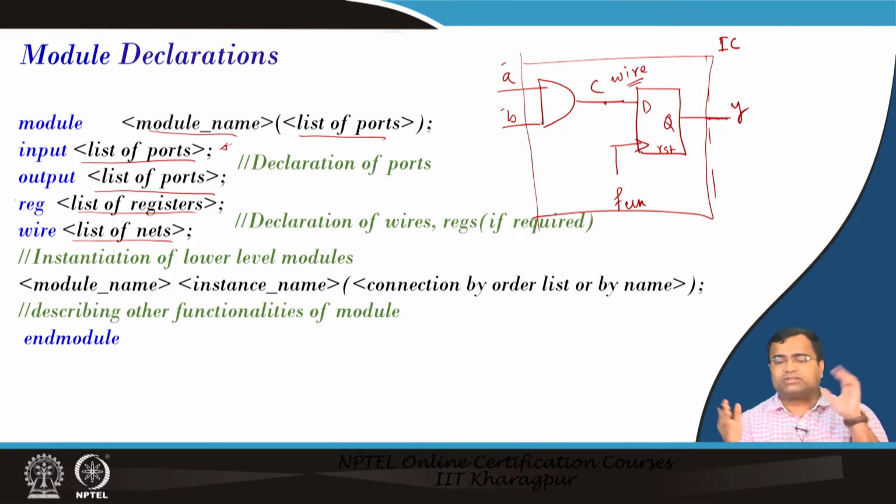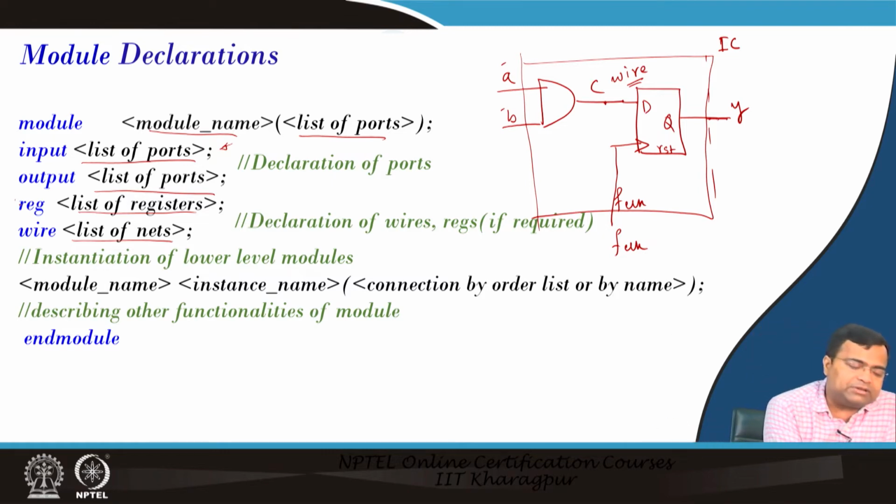So these ports are outside, but this internal variable and another clock can also be output, but this internal variable is not connected to any of these ports, so you have to define it like a wire. Sometimes you may put another block after a register, so you have to define which one is a register and so on. So you have to declare, that means other than output.